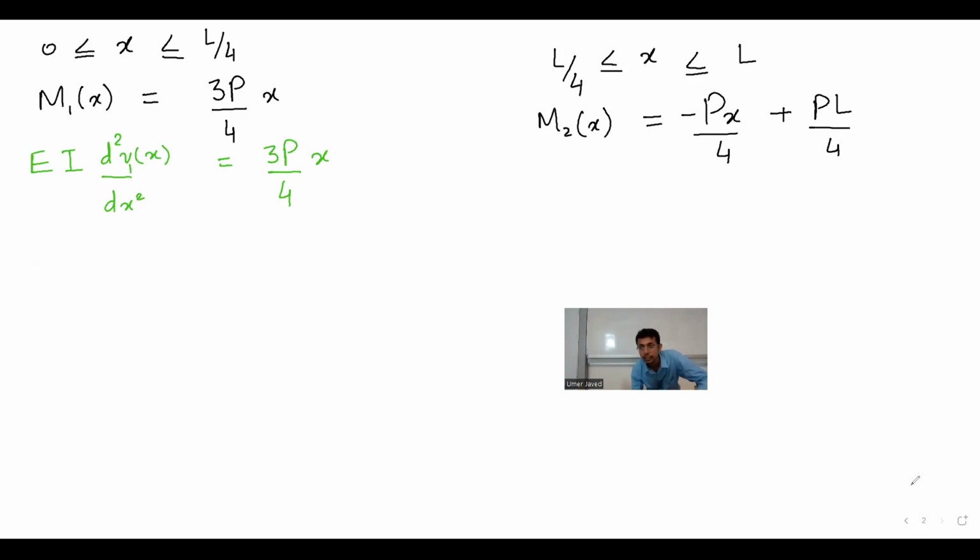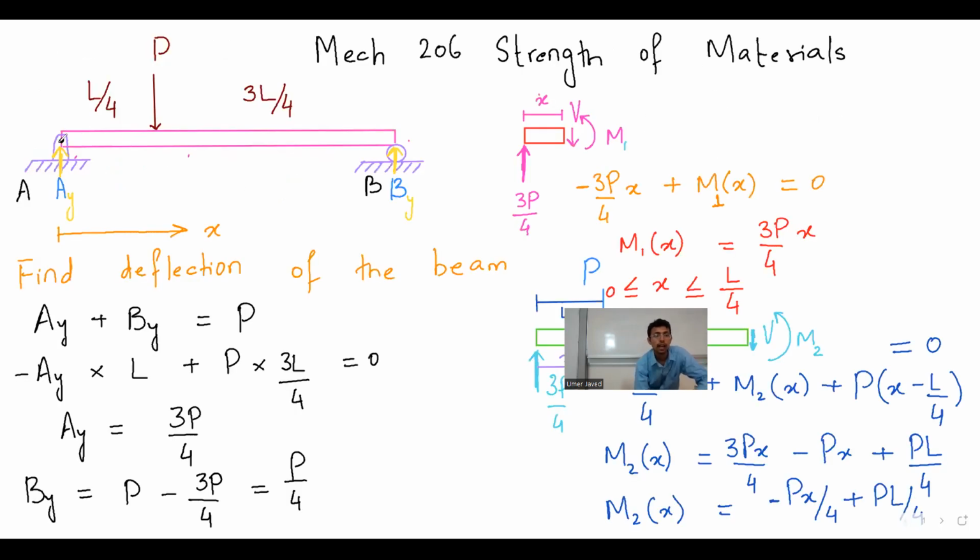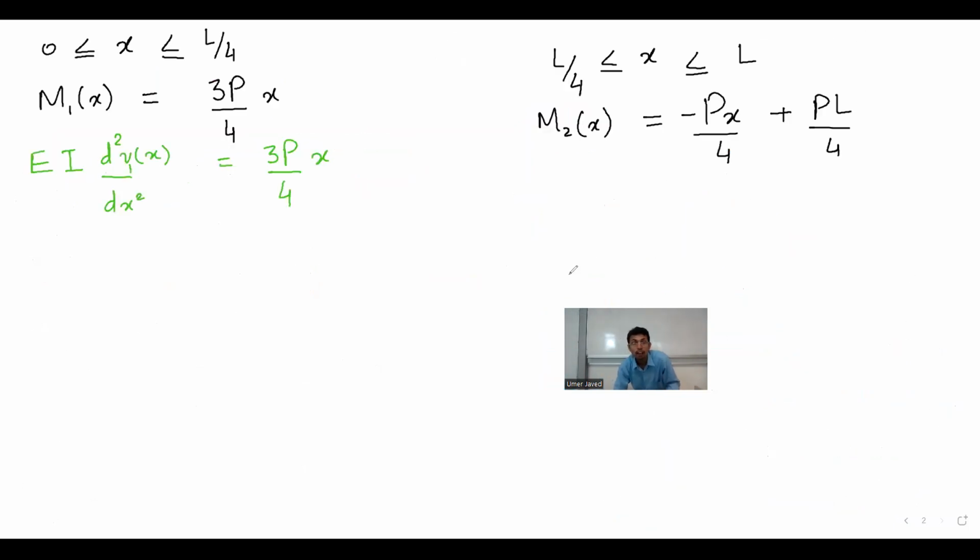What you have to understand is that this beam is not as simple as you think. If I ask you how the deflection is happening, all of you will tell me it will happen like this. Follow me. Agreed? Now it will happen like this, correct? So there are 2 portions of the deflection. One deflection is between 0 to L by 4, a certain polynomial. Another portion of the deflection is between L by 4 and 3L by 4. So if you want to put a 1 here, that's fine. And if you are not putting a 1, then definitely add a little comment: this is only true between 0 and L by 4.